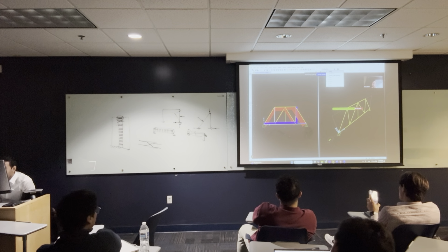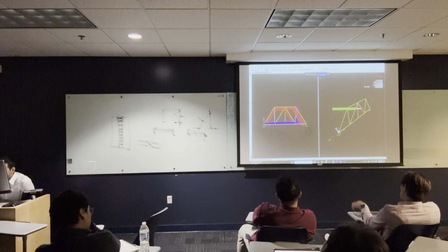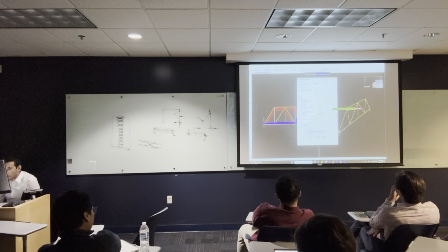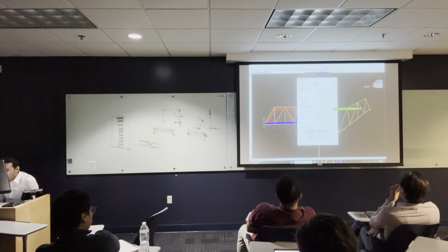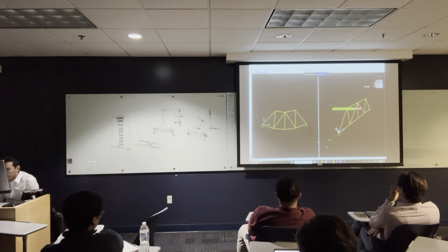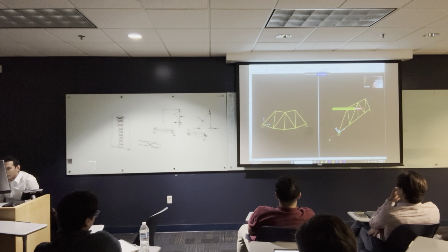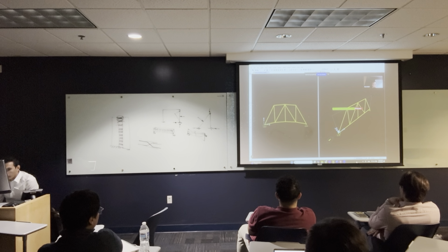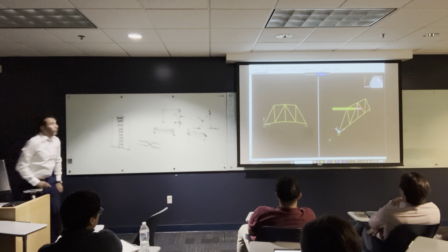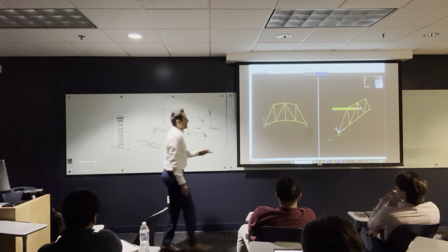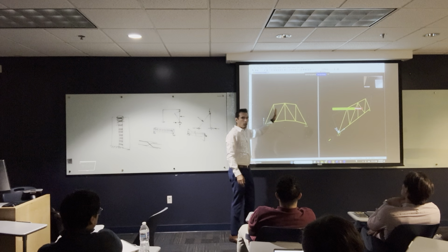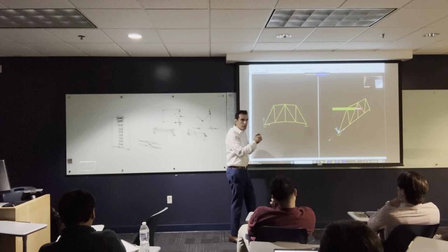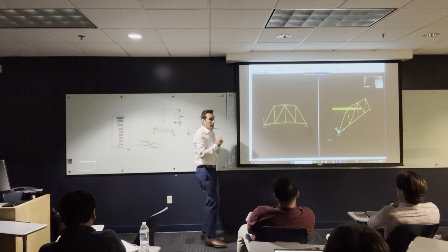Let's see if you want to show the deformation. You can show also the deformation from the load combination number 1. And I'm going to also say okay. And here it shows you what the deformed shape looks like right now. You will tell me, oh, where's the live load? The live load was a little bit smaller than the dead load, so it doesn't show how the structure is moving that much, but it's still there.